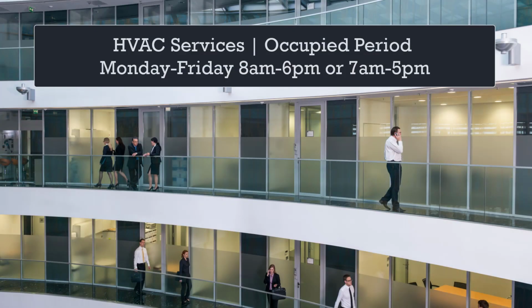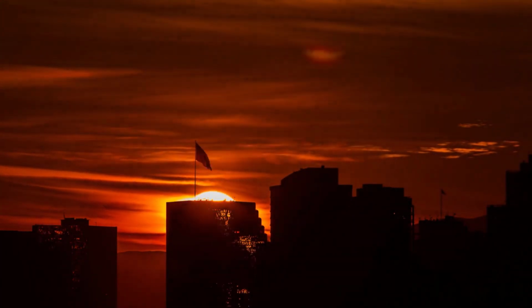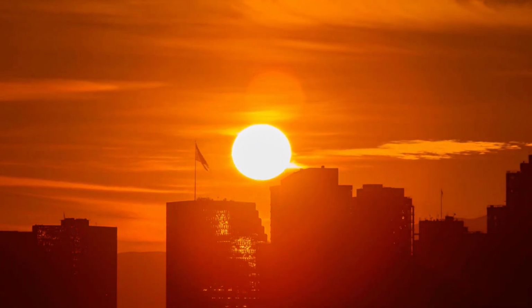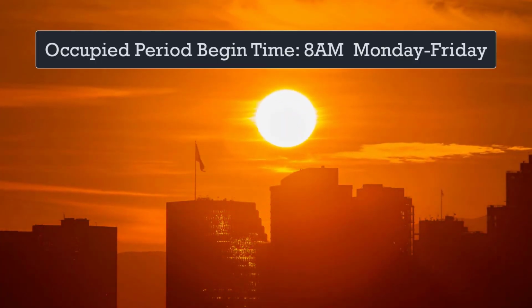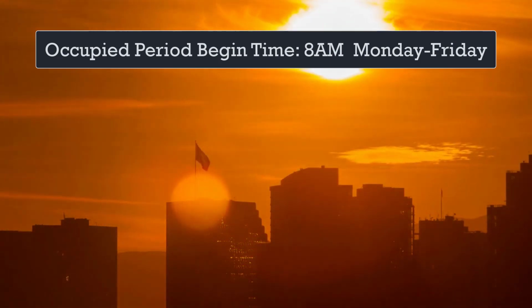Most commercial office leases stipulate HVAC services 10 hours per day, Monday through Friday, typically 8 a.m. to 6 p.m., and in some cases 7 a.m. to 5 p.m. From an energy controls perspective, the period of mandatory HVAC services is referred to as occupied period or occupied mode. To provide human comfort conditions outlined in the landlord-tenant lease, building operators must start HVAC systems at or prior to the occupied period begin time. For our Optimum Start simulation, we'll define the occupied period begin time as 8 a.m.